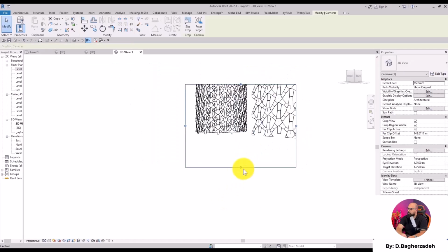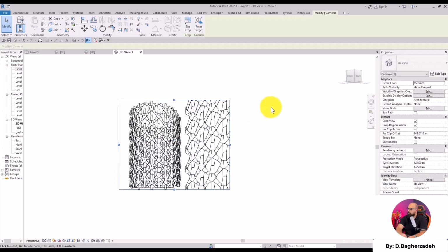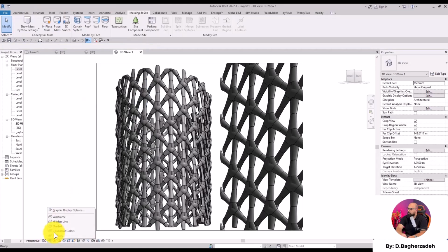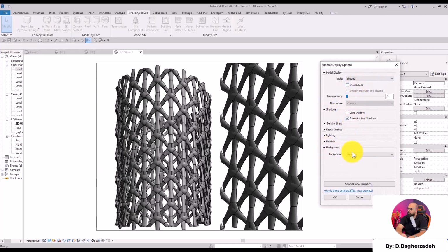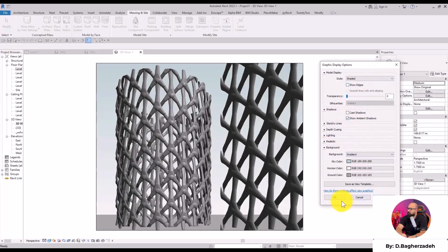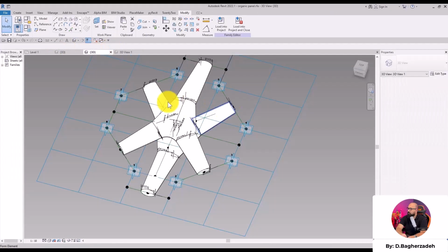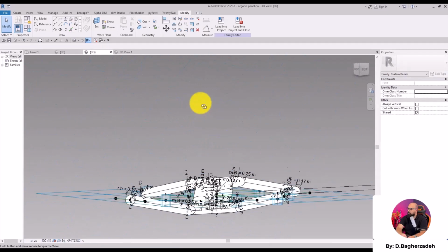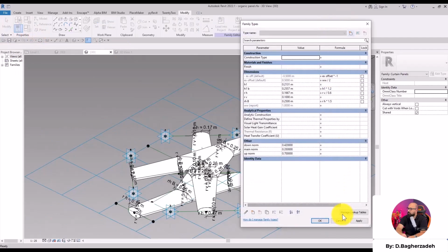Okay, let me modify the boundary a bit. And also deactivate the mask. Now graphic display unshaded. Then deactivate the edges. And also let's give it a nice background. Awesome. This is good. Now, the thing is, guys, if I go ahead and increase the scale here, the viewport would get extremely crowded. And well, at first glimpse, it might seem quite complicated and confusing.